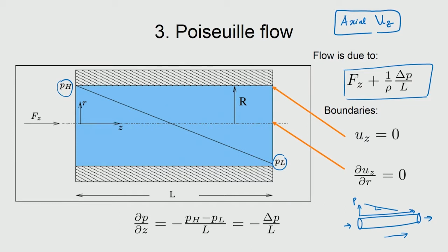Now, the inner walls of the tube are assumed to be rigid, smooth and so on, and so the boundary conditions that are applicable are that the velocity at the inner wall is 0. This is from the no slip condition. We also want to say that along the diameter there is a symmetry, which would mean that the velocity profile should have a finite value at r equal to 0, or you have a slope that is 0. Both would mean the same thing when we are solving the equation, but we need to use one of those two principles at the center, that is either the symmetry or the velocity being finite.